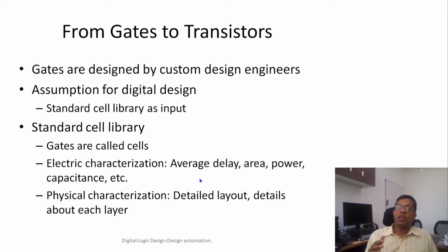It should be able to take care of the fan-out capacitance, or the effect of fan-out. So to take care of the effect of fan-out, the design of the gate also needs to be modified so that it can still be high performance. So sometimes multiple variants of the gates would be designed based on the circumstance: if it is to be used in a case of high fan-out, then the internal design would be slightly different.